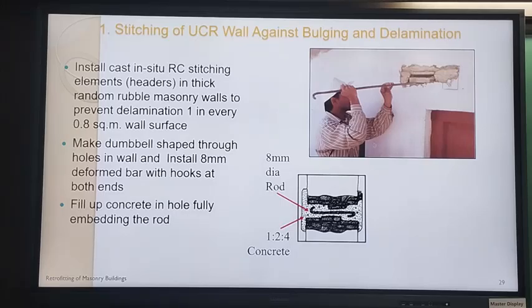And also, basically the construction in Latur and construction in Uttarakhand, although random rubble masonry, mud mortar, the stones are of completely different type. Latur was basalt, very different. Uttarakhand has different stones which are flat. So removal of stone, the whole process changes.